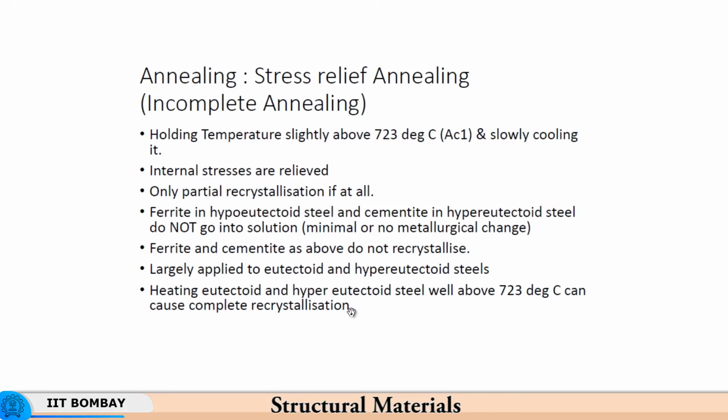internal stresses get relieved primarily by a decrease in the yield stress of the material. So, the yield stress of the material reduces below the magnitude of residual stresses present in the material, and so very local plastic deformation takes place, and there is nothing else happening.